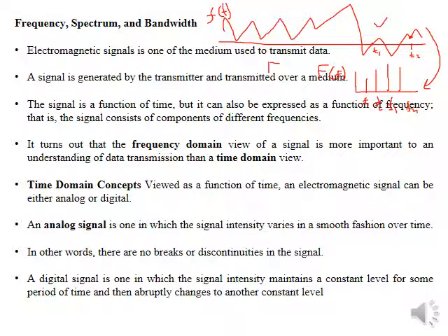And do you remember how to convert that? Yes, by using Fourier transform, as we have learned in previous lecture. So in frequency domain you can see what frequencies exist in this signal, but we are missing one thing here, that we cannot find time in frequency domain.